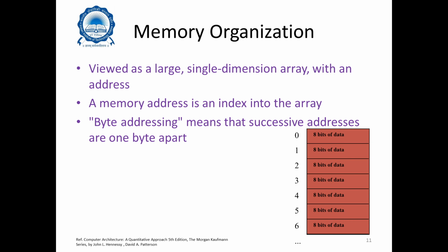What you see in all of these things is that a good design demands good compromise. The compromise chosen by the MIPS designers is to keep all the instructions of the same length, because eventually the plan is to make a good design. We will see what that design is gradually when we enter into the course, how the processor actually looks like, thereby requiring different kinds of instruction formats for different kinds of instructions, right? It is obvious, because you cannot just have one instruction format to do all kinds of instructions.